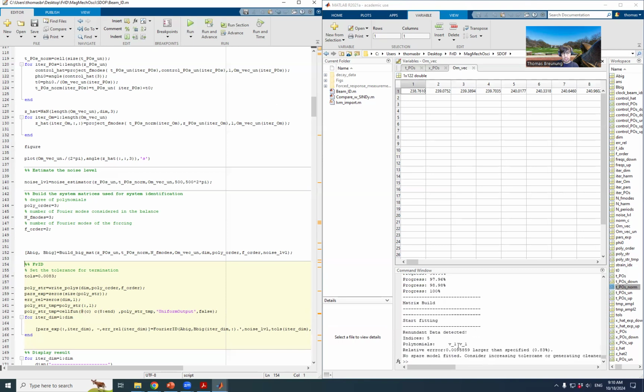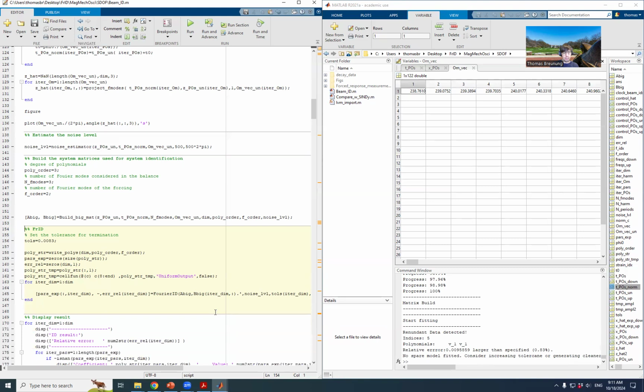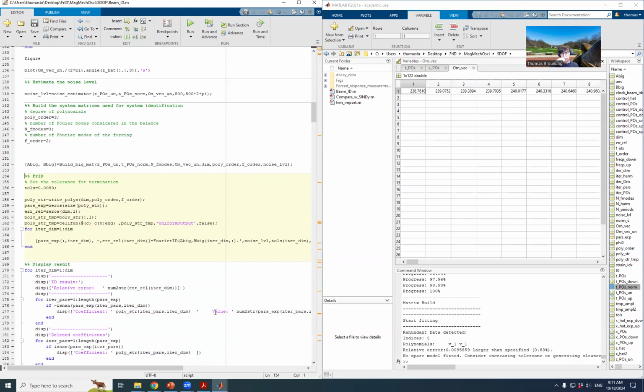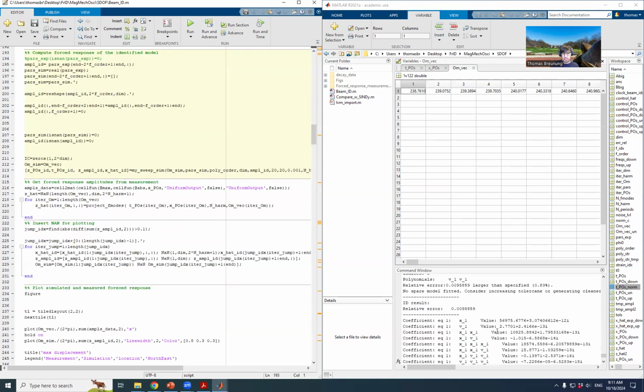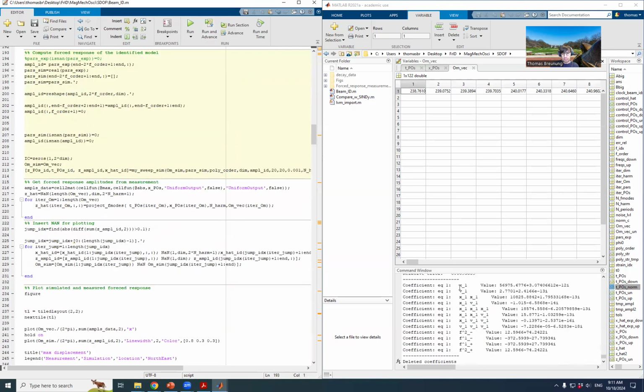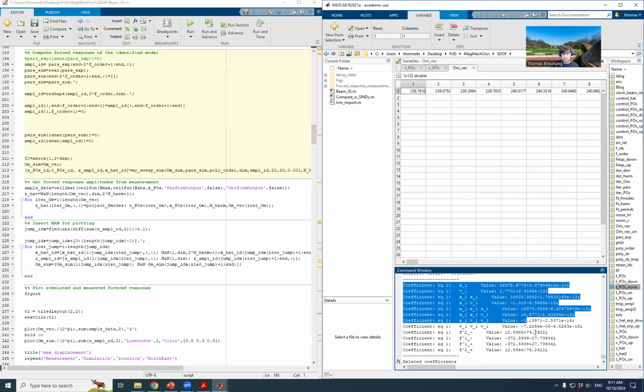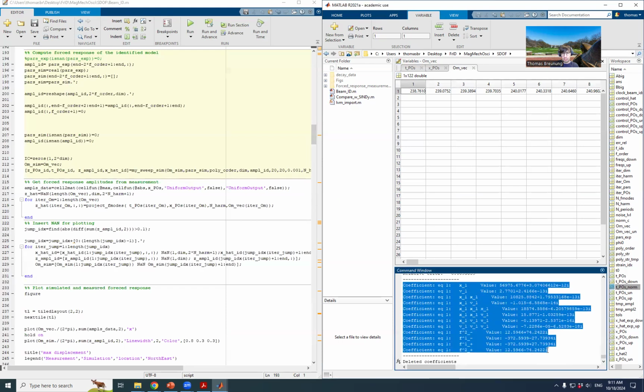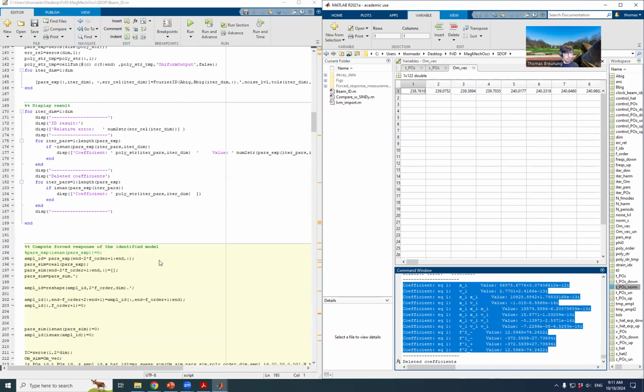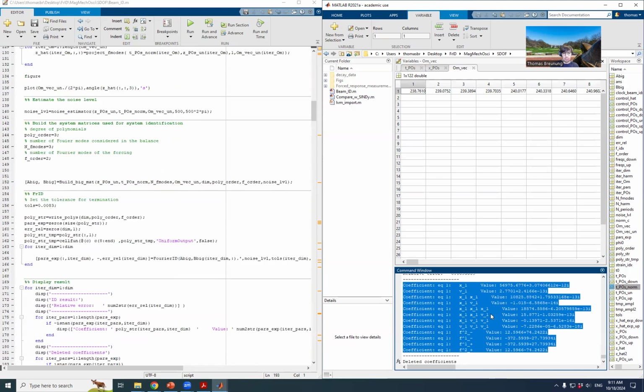So now we see that the relative error is 0.009, which is larger than the specified tolerance. So we cannot sparsify the system. So we cannot reach the tolerance we want to have. We could technically display the result, but this is a non-sparse system, a lot of coefficients, which is questionable, but we can also just increase the tolerance.